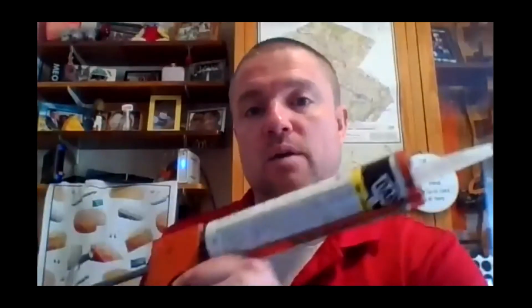They also make peel and seal products in a caulking tube, so you would need a caulk gun. All right, load it up, and you can apply it with a caulk gun. If you're going to lay a bead down with a caulk gun, I was always told by my father to practice, because you want that bead to look good. So find an old piece of wood, try out the bead one time, see how it looks, and get comfortable with the caulk gun. If you're not a fan of the caulk gun, they do make permanent caulking too, of course, which can be removed.